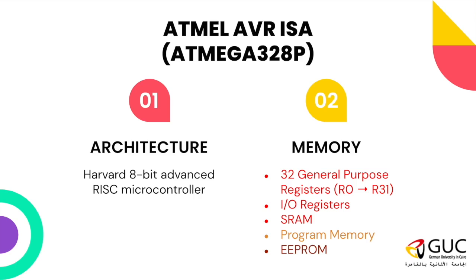So I was checking on this flag. Here in our AVR architecture, the zero flag will be a bit inside one of the I/O registers. So if I want to know the value of the zero flag, I'm going to read this bit from a particular register.